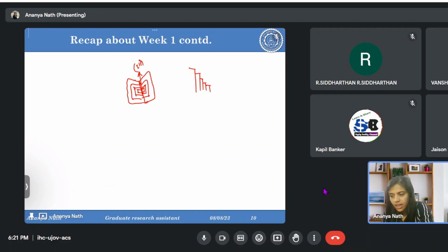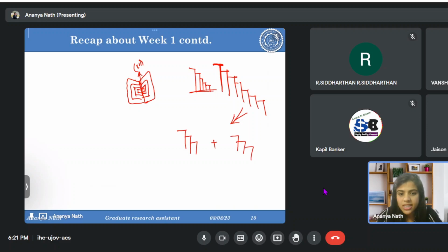Understand this thing, this growth cannot be restricted, but what we can do is break the chain. If this growth is growing like this, and somehow we can go from this to this, because wherever there is primary silicon it will grow, but if we can somehow break the chain, the brittleness will not be that much.